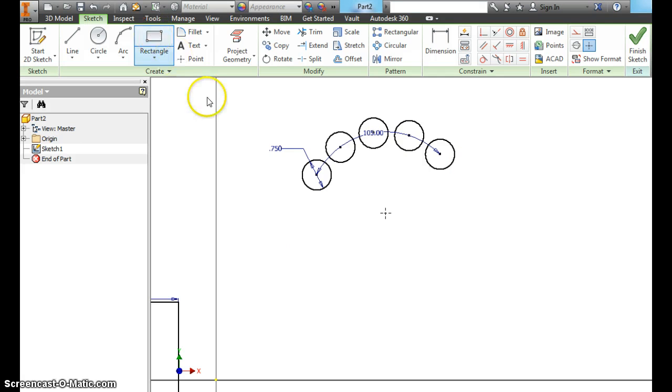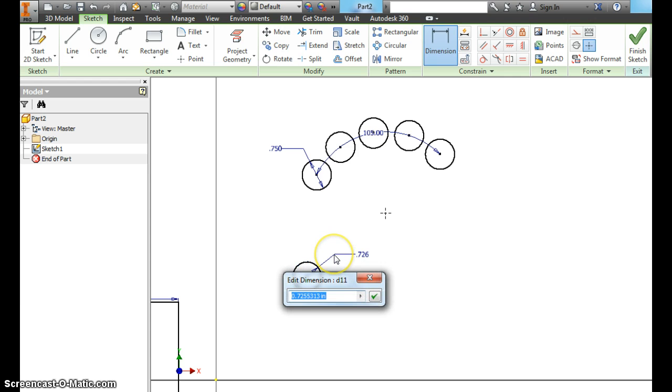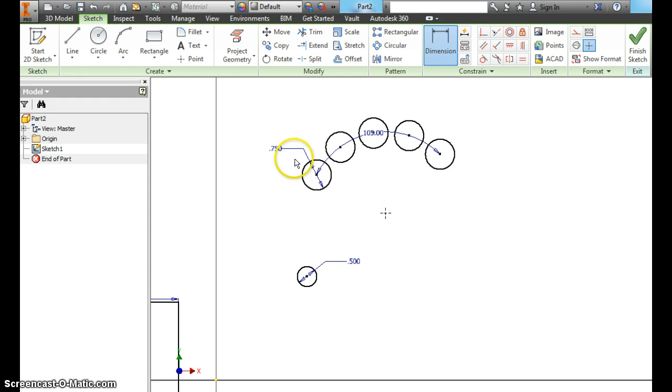Let's look at a rectangular pattern. Whoops. Okay, I chose rectangle. I don't want to do that. So right click, OK. I want you to draw another circle. Okay, dimension it to 0.5 inches. Pretty small, which is okay. We're going to make a vertical line. Make it above the circle a little bit. Right click OK to get off of that.